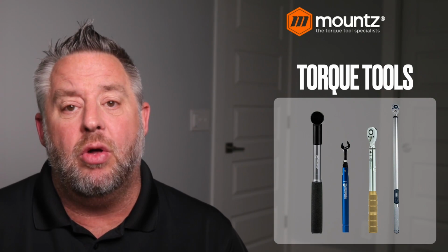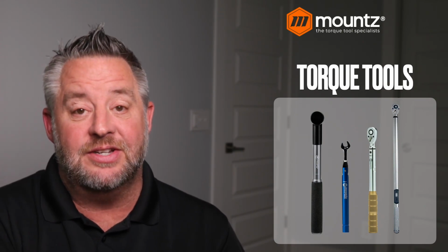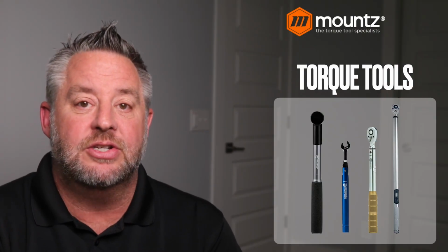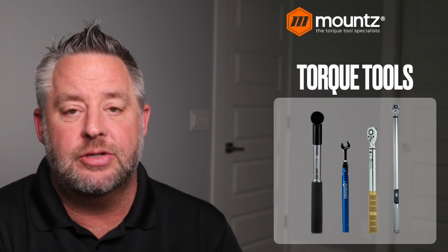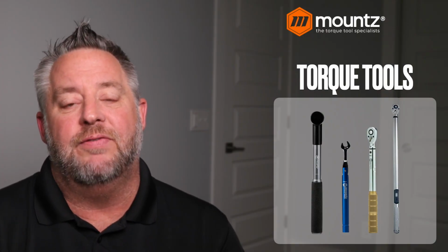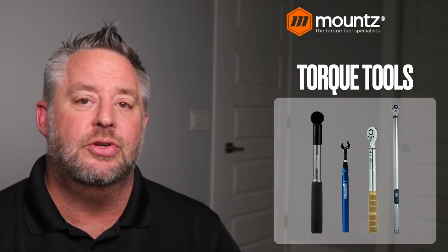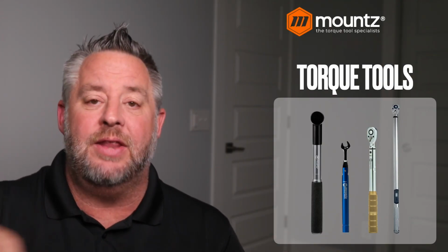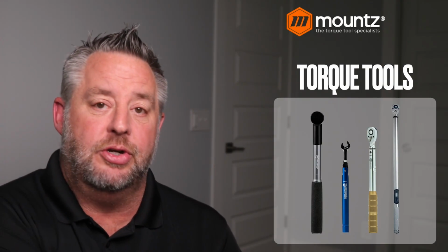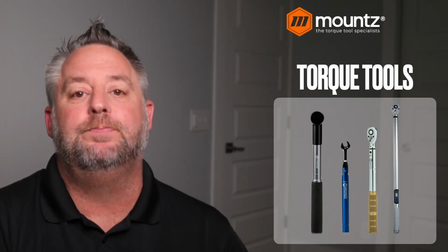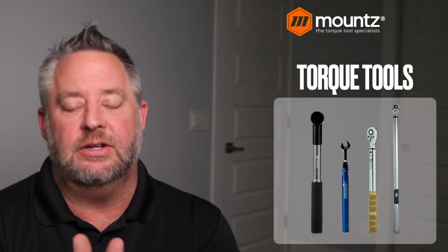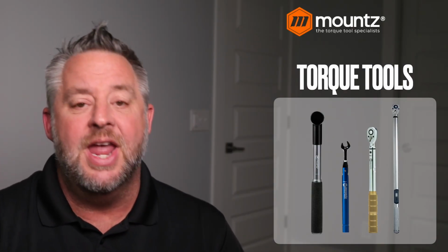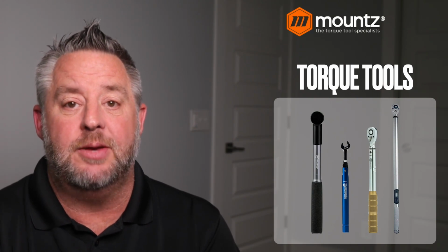These wrenches all work off of the distance times force ratio. The only one that doesn't is going to be the cam over style wrench, because the fulcrum point on this particular tool is at the end of the wrench. And so we can hold it anywhere we want up and down the handle. It's always going to produce the same amount of torque. If we were to hold it at 2 feet or 1 foot, it's always going to slip and it will always produce that same amount of torque.